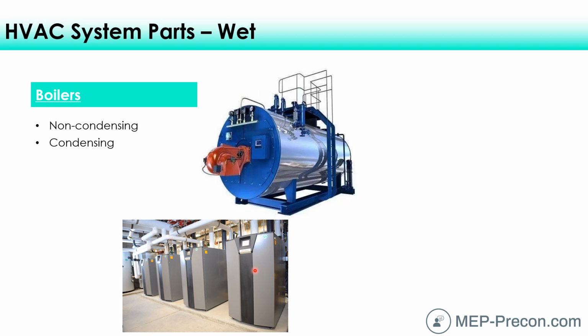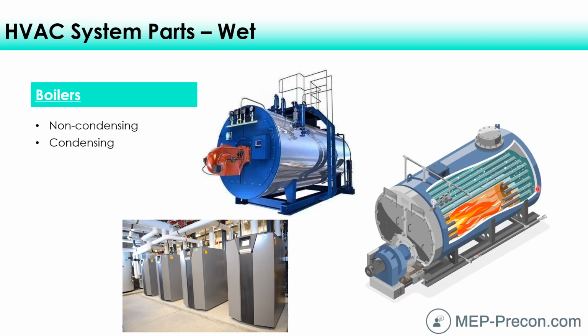But when you wring that much heat out of the flue before it escapes the building, what tends to happen is it cools down to the point where the products of combustion condense inside the flue. They condense on the walls of the flue, and they'll drain back down inside your boiler. And those products of combustion can be pretty aggressive, pretty corrosive. So not only could they rot away your flue, which is not a real big deal because you could replace that fairly inexpensively, but if they get down to your heat exchanger, they could rot away your heat exchanger, and that can be pretty expensive because inside that heat exchanger is a lot of money.